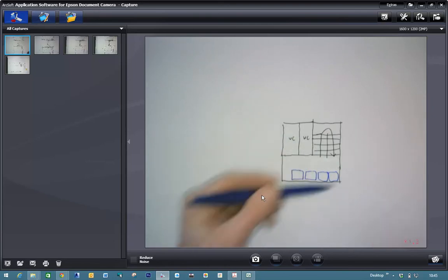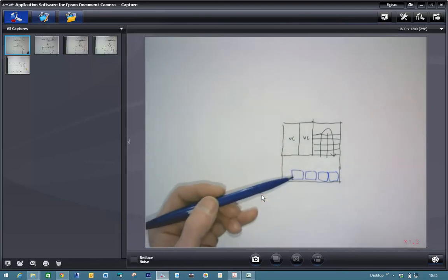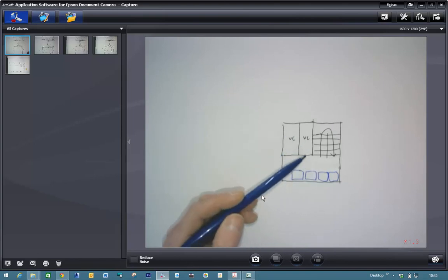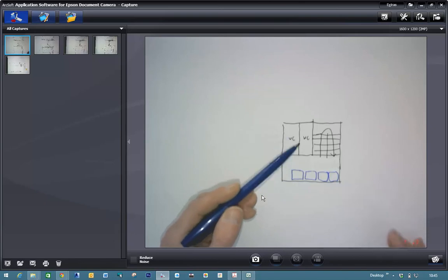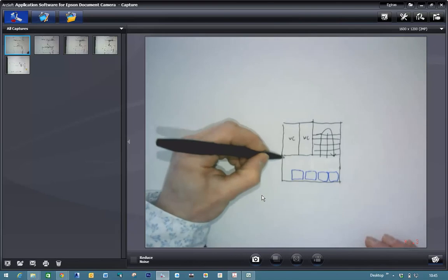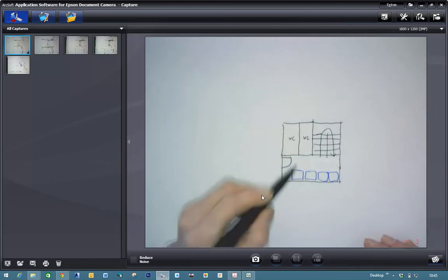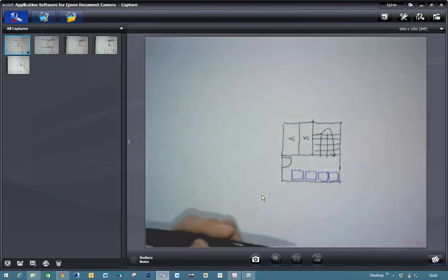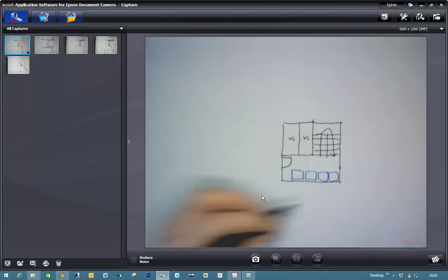And this kind of layout is often better because the important thing is you're allowed the WCs to open onto that escape stair. Okay, you couldn't do that with an office, a classroom, anything with a fire load. But WCs, you're allowed to. And then the other thing is that your door swings must not impinge the flow of the stair. Obviously, if you're trying to escape down a stair and there's an open door in the way, that doesn't work. But that's the basic principle.